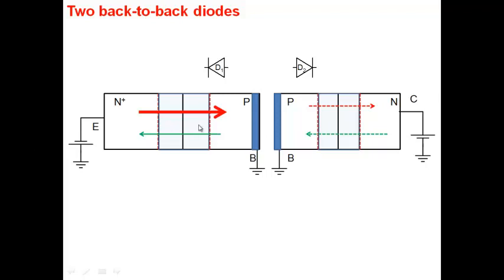I have forward biased one diode here. So forward bias, which means currents are flowing, significant currents are flowing, IN and IP are flowing here. And I have another diode here. This is ground, and of course, because it's reverse bias, that's why I've shown with the dotted line, the currents are very small, almost negligible here, and this component is also very small. And so we have these two diodes, independent diodes. If you short them together with a wire, it's not going to make any difference, right?